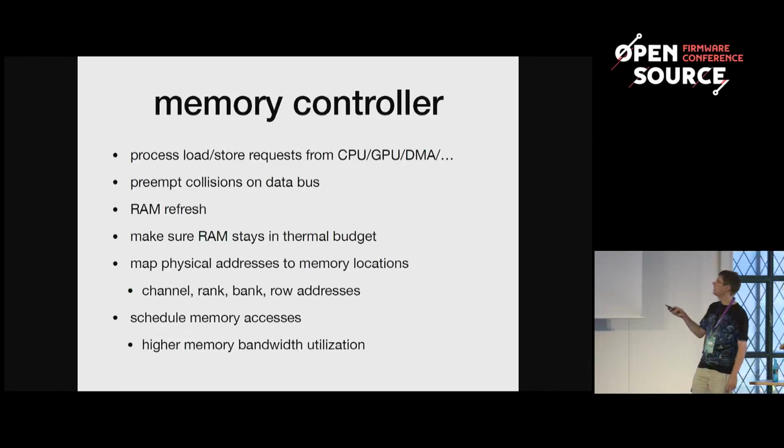Yeah, and also it has to make sure that the RAM stays in its thermal budget, because when you access the RAM at full possible speed, after some time it will heat a lot, and then the chance of bit flips increases, and possibly also destruction of the chip. But I haven't seen memory being destroyed by accessing it too much, but yeah, you should make sure that that doesn't happen.